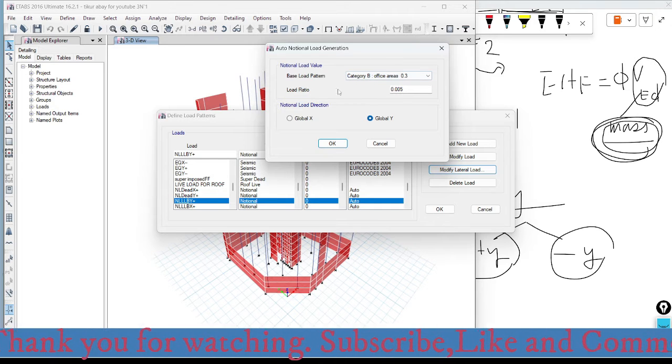Because we are defining the variable load for seismic conditions, during the application of the live load for the seismic condition we need to use the reduction factor phi 2. Okay, now here the load ratio is 0.05, and here we need to apply first in positive y direction. So later I will also define for the positive x direction.